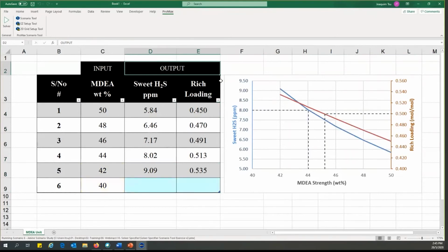We have used these kind of things to do sensitivity studies. So we can vary our flow rate by plus minus 10%, or vary our reboiler duty by plus minus 10%. And this will let us see how robust our system is in a very objective way. And for some of our clients, they have even opted to tie their historian with ProMax.